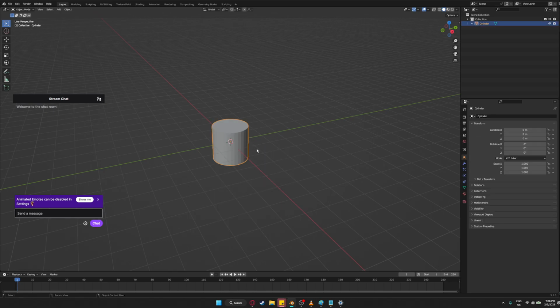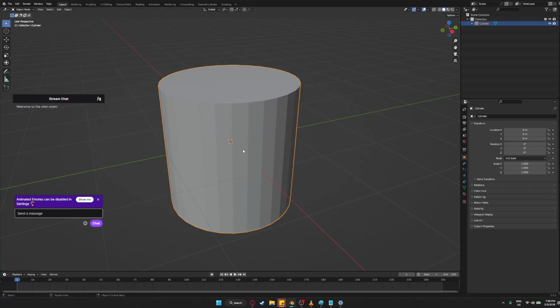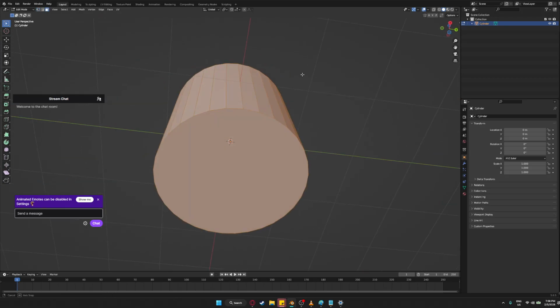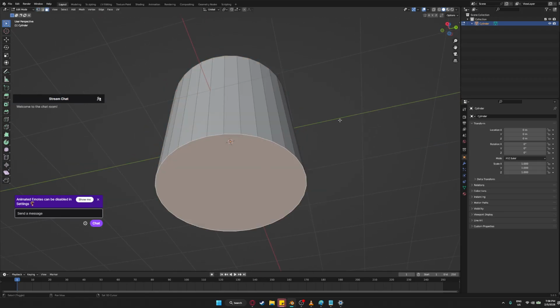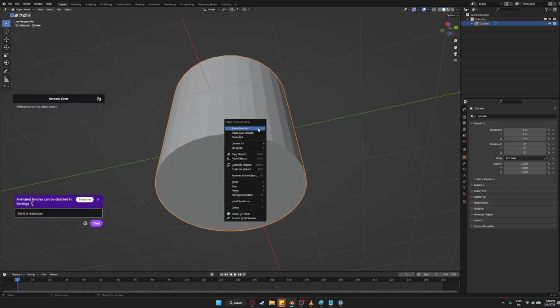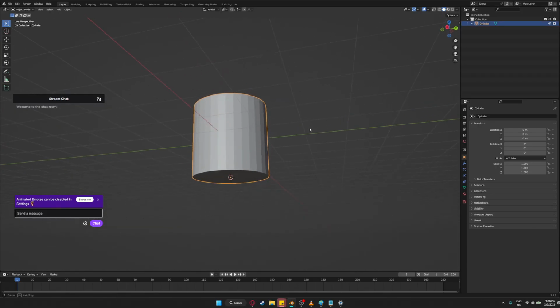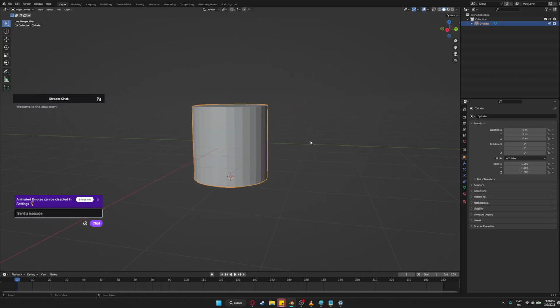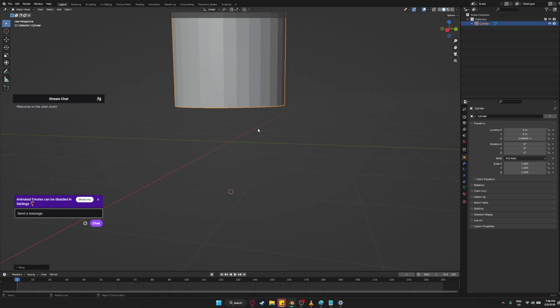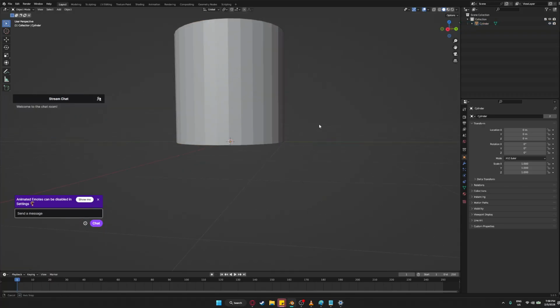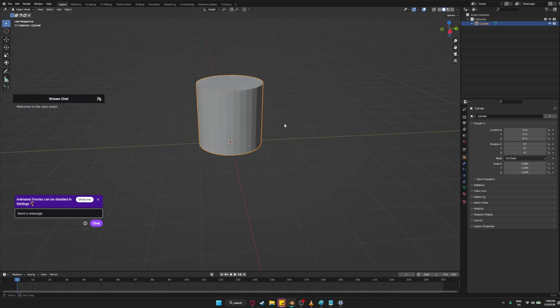So we're just gonna cylinder that up, and then we want to change the base of this. We're switching into edit mode. Select that. Cursor to selected. Back into object mode, set origin to 3D cursor. Don't really have to do that. Wrong button. Hold on. Just grab that up, and then cursor to origin. Alt G. Ta-da!